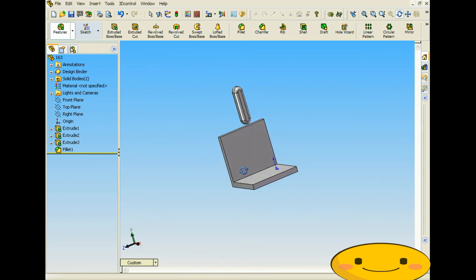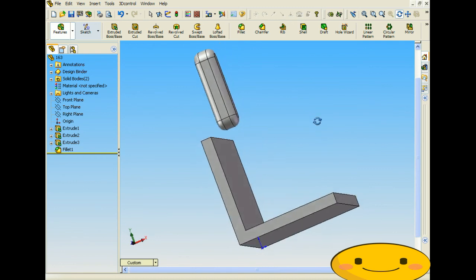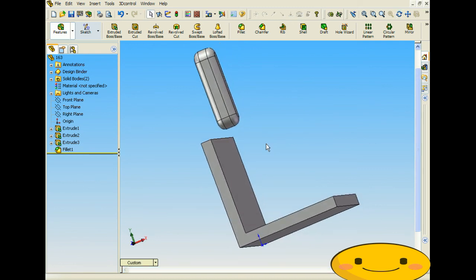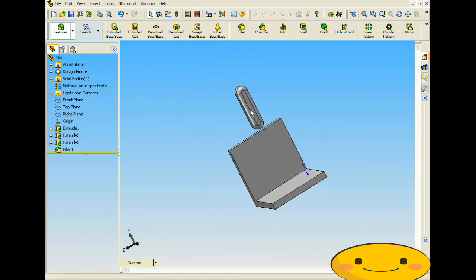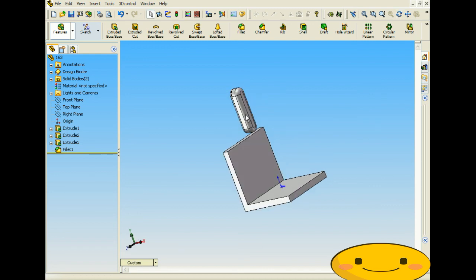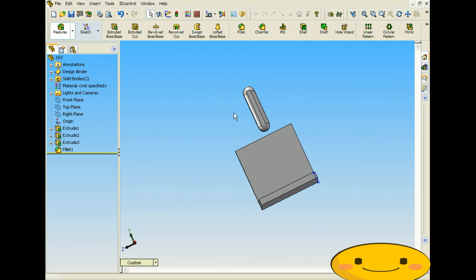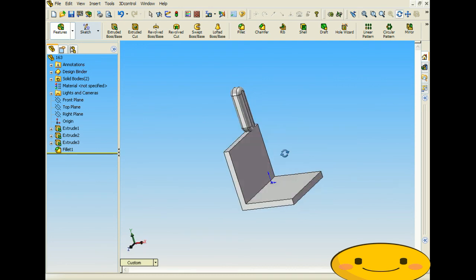Now in the prior tutorials, what I've covered with the surface push is that you have a body selected through the drop-down menu, and you use that body to create a deform. In this tutorial, you're also able to select a body that's created outside of the whole menu and use that body to deform your feature. So we're going to be using this body up here that I've already created beforehand, and we're going to use this to push into the surface and create our surface push.